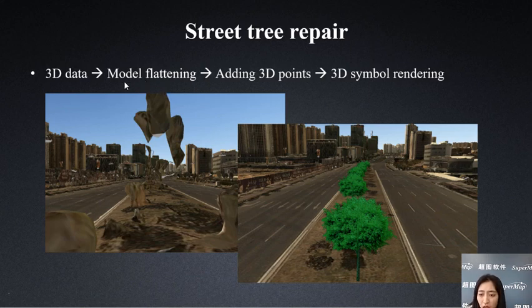You only need to draw a polygon in the area you want to replace and edit, adjust the flattening range, and ensure the accuracy of the flattened polygon. The oblique photographic data located in this polygon is flattened into a plane.